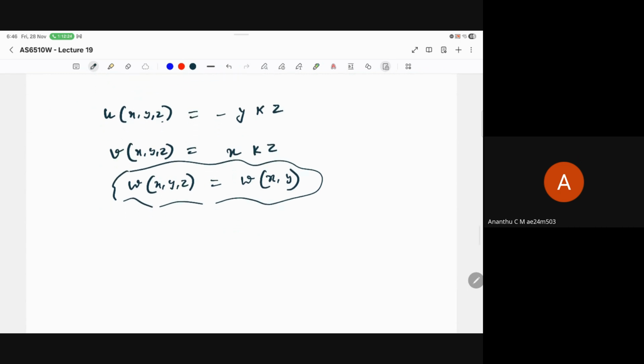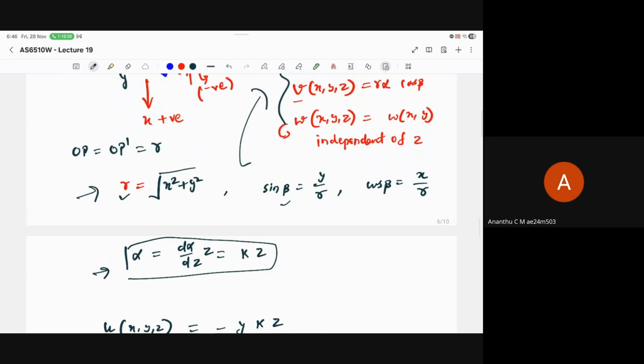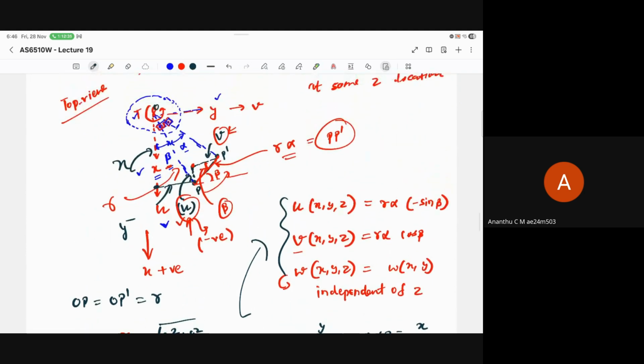Okay. So we have now defined the values of the displacements, right? So when you apply the torque, there will be deformation. If you consider a particular point, that is going to move because of the torque loading. Basically, it is going to rotate, and because of the rotation, we have obtained the displacements u, v, and w is independent of z.